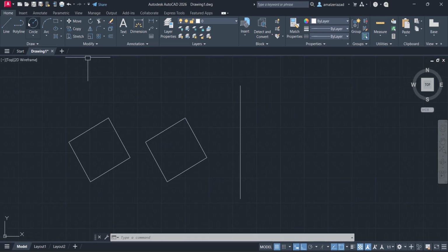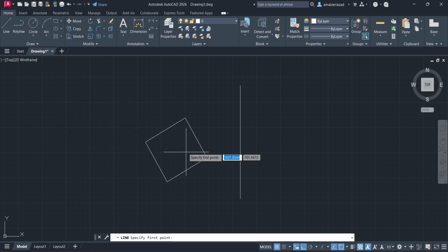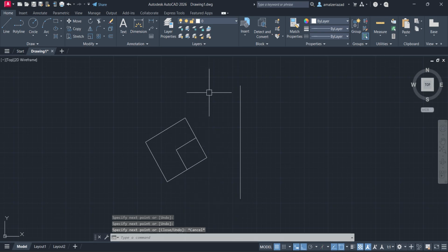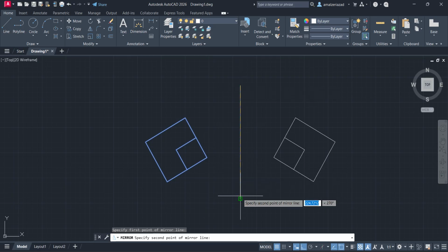Before that, I'll just create some structure in this, something like this, so that you can differentiate whether it is mirrored or not. Now you can see how it is. I'll select this and go for the mirror from this point to this point. You have to choose 2 points in a vertical line, then only it will copy. If you change the orientation of the points, suppose as of now I chose it as vertical, and if I take it in an aligned direction, then with respect to that angle, the angle of the copy will change. Anyway, I'm going to show you.